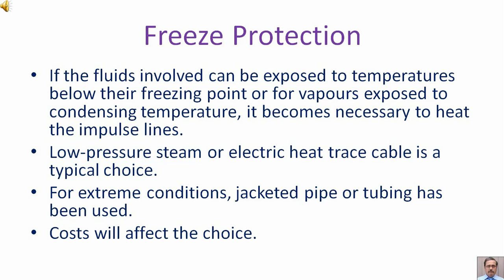Low pressure steam or electric heat trace cable is a typical choice. For extreme conditions, jacketed pipe or tubing has been used. Cost will affect the choice.